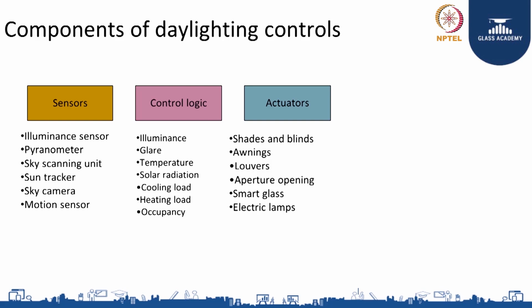Usually we will think that as there is no sunlight, why would I need to control the daylight devices. But in this case, in the night time when the outdoor temperature is so low, the building would be losing heat, and we might like to control the shade and bring down the shade, not to prevent any light from coming inside to outside or from outside to inside, but for increasing the insulation on the window so that the heat that is going out from the building is reduced. So the daylight control systems can also operate on temperature.